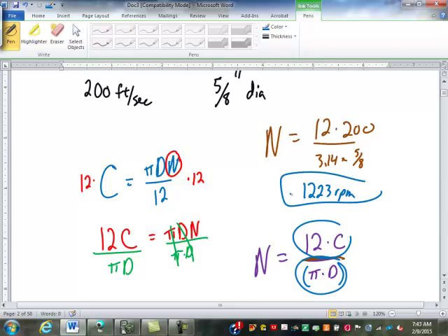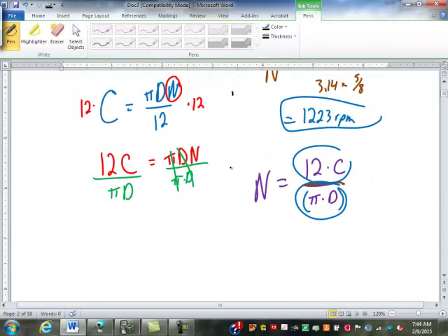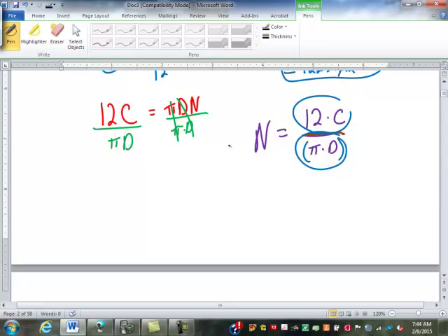That might be just a little fast. Well, 200 is a pretty hefty surface cutting speed. Yeah. 200 would be for aluminum, and only if you have a pressurized coolant for aluminum.